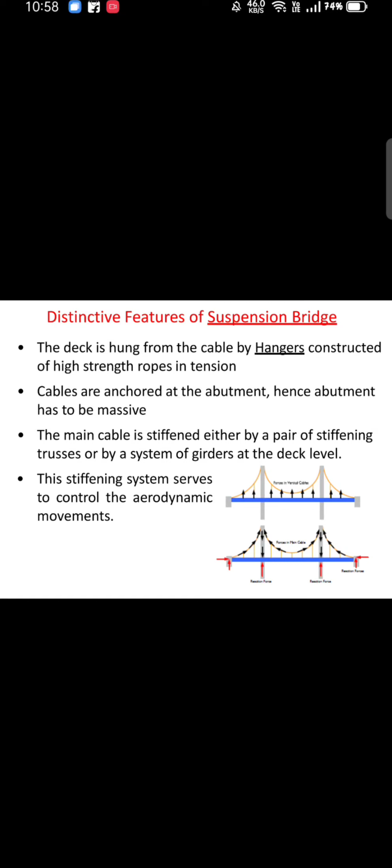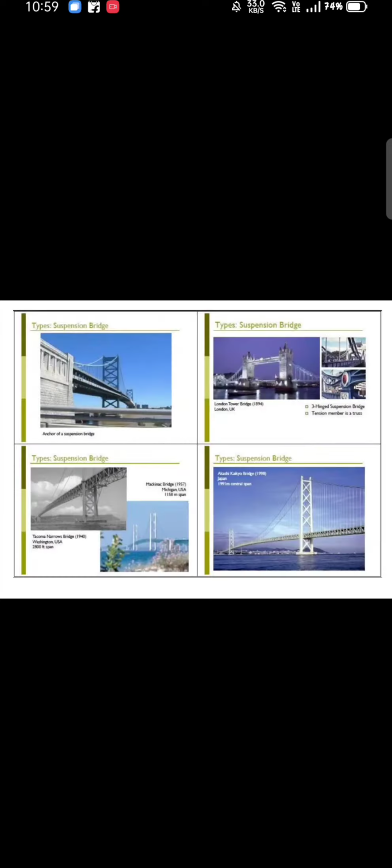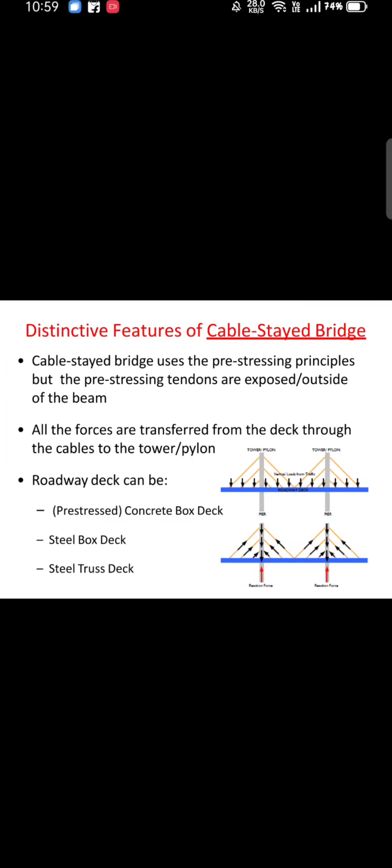When the load falls on the bridge, the suspenders carry the load to the column and then to the foundation. Like this, the loading pattern will be carried over. The height of the main towers is the major disadvantage. If there is an airport nearby, it can be a disadvantage there. Generally it spans from 600 to 3000 meters. You can see various suspension bridges, which are age-old.